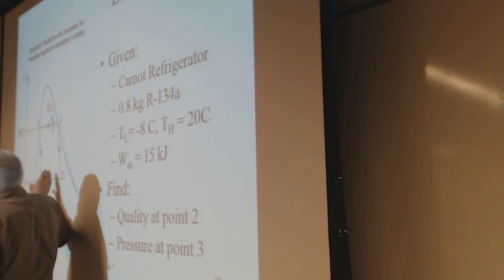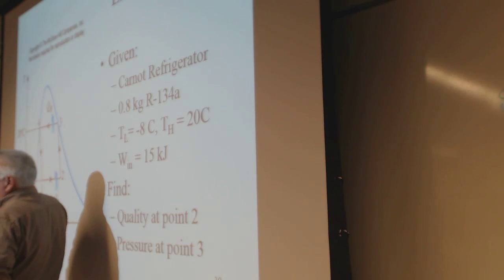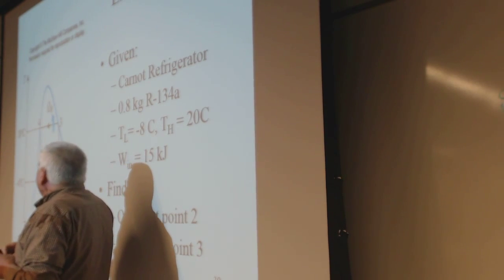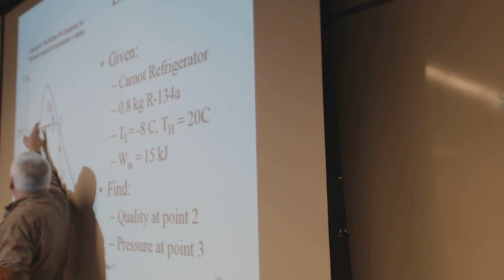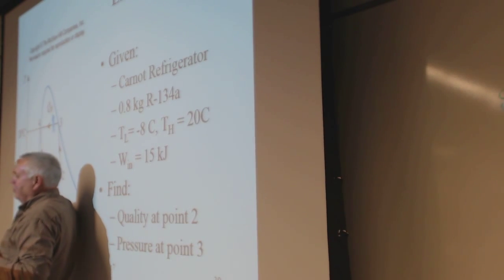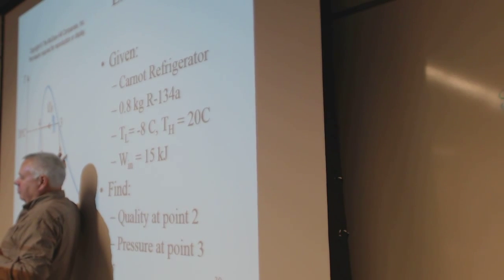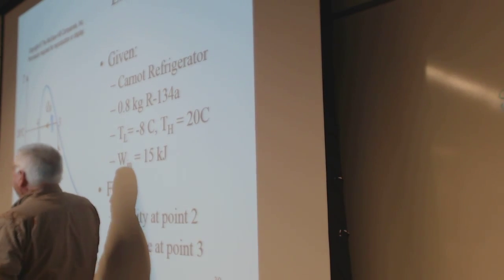We don't have to actually get all of the points here, but once we know the Carnot efficiency, then if we know this Q high, we know the efficiency, we can come up with Q low, and come up with the amount of work, and undo the problem.